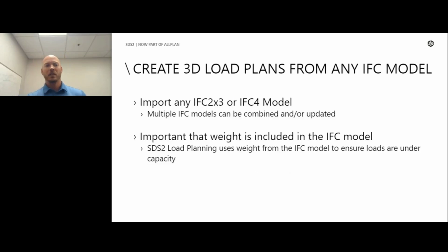Just to expand on those topics a little bit more, SDS2 load planning will take any IFC 2x3 or IFC 4 model. That means we can work with SDS2 itself for detailing, whether you're using Tekla Structures to do your detailing, SolidWorks, any number of different softwares that produce an IFC file and include their weight with that IFC file, we should be able to use. A couple things to note there, we don't have to bring in the whole structure at once. Some of you are working on larger structures or projects where you're probably releasing certain portions of that model at a time. So you're able to export an IFC file of just what you're releasing, just what needs to be planned out. And then we can combine the different IFC models into one project within SDS2 load planning.